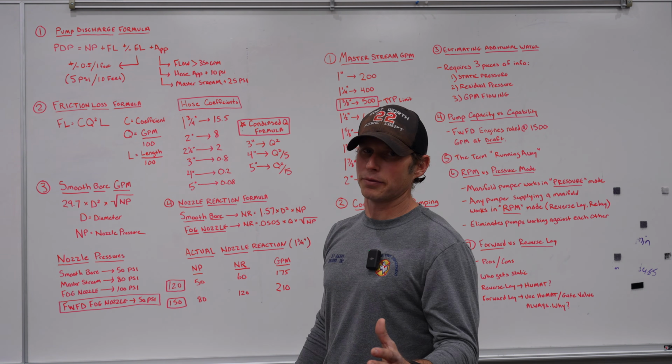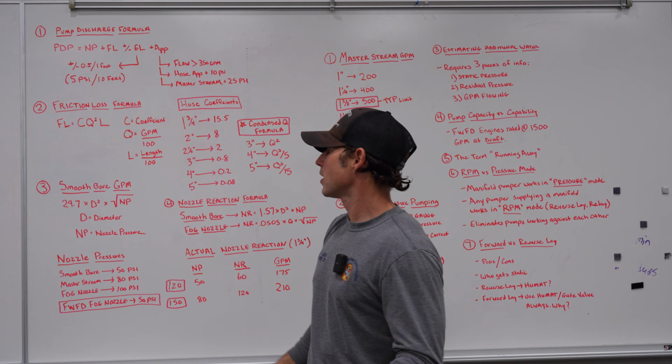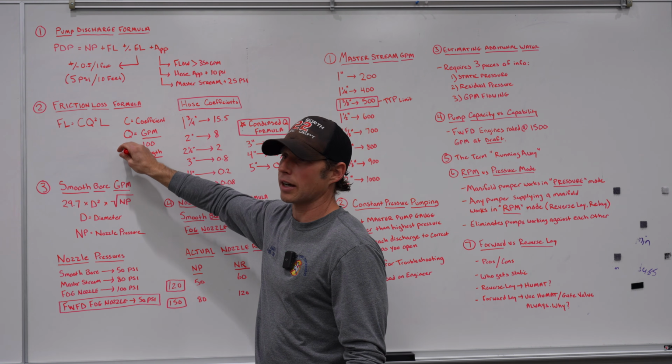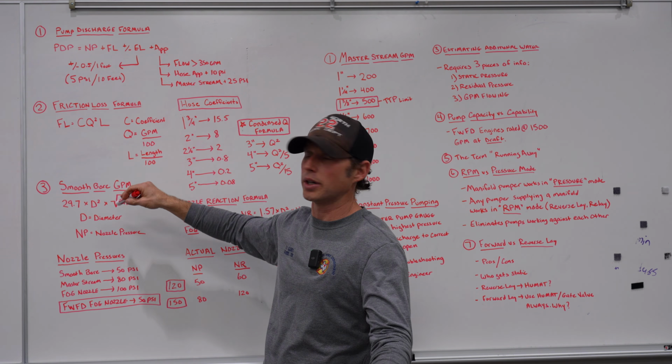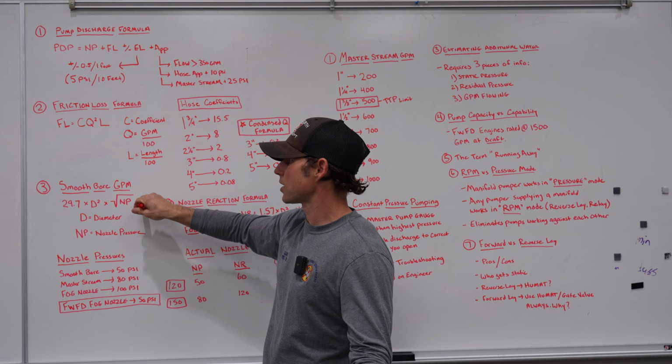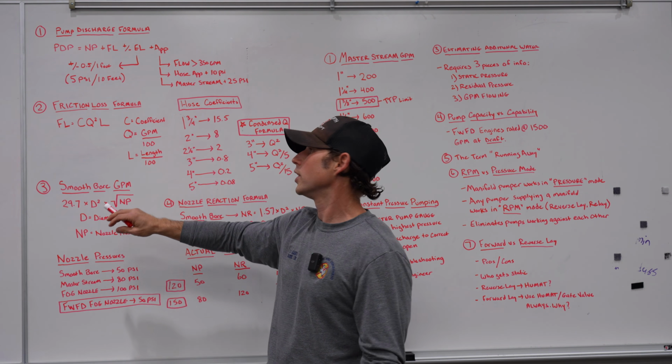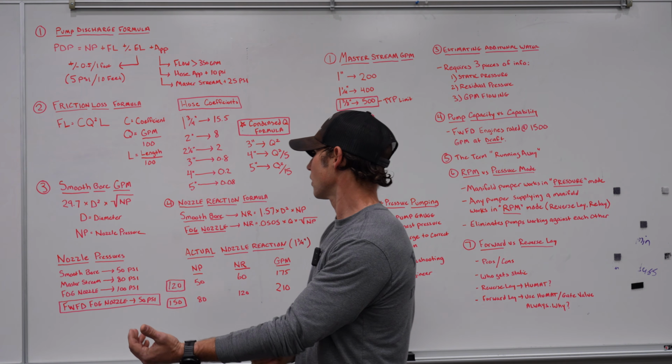Don't get confused by that. It's just that extra step. If you can't figure out the gallons per minute, it's probably because they're throwing you a smoothbore tip size, and you've got to figure that out before you plug that into the Q.